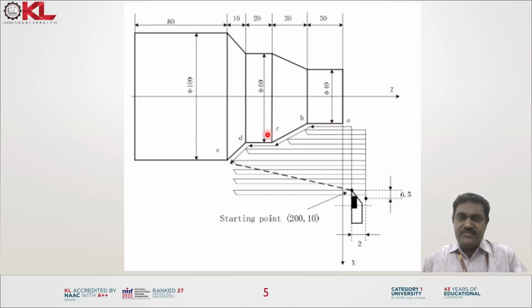Okay. So with this final shape, whatever amount is mentioned in the program, that finishing element of the material is left over and the remaining material is removed in this process. Okay. So during the rough cycle, the entire material is removed stepwise, step by step.